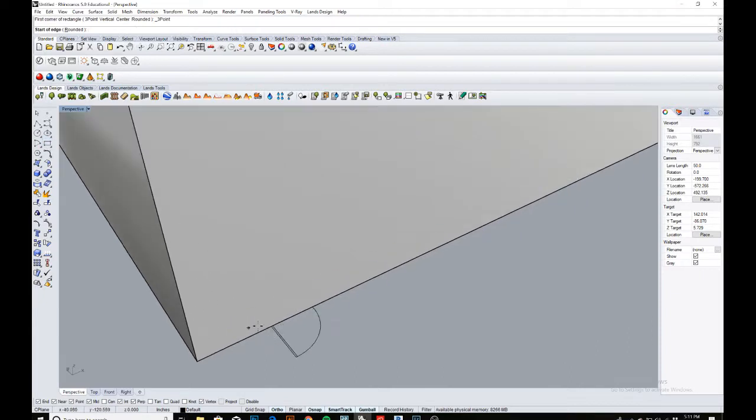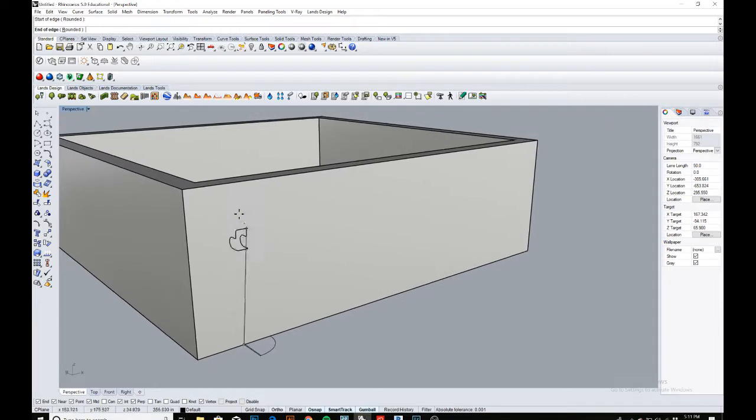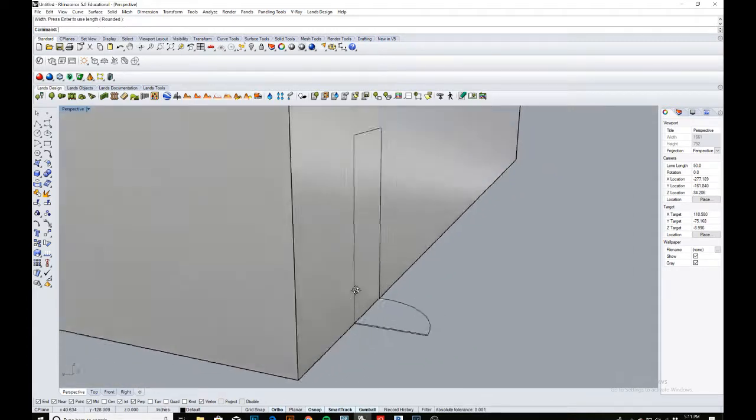And then the final part, we're going to make these openings for these doors, which is in my rectangle tool. We're going to go from the outside of this door. And what I like to do is I'm just going to put my mouse at the top. Don't click, but type the dimension, which is 84, and enter. And then you can click. And then you can just simply put your mouse on the other side. Now that's perfectly drawn to that surface.